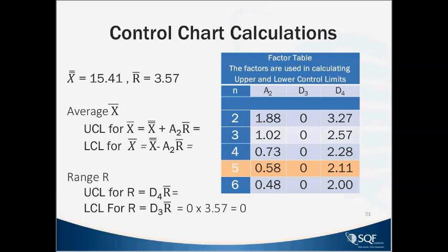There was an error in that page 16. So on the last line where it says average of range and it's an S bar, that should be an R bar. My mistake, I didn't catch that. We do use S bars, but that's for a different type of control charts. For here, we're looking for the average range.